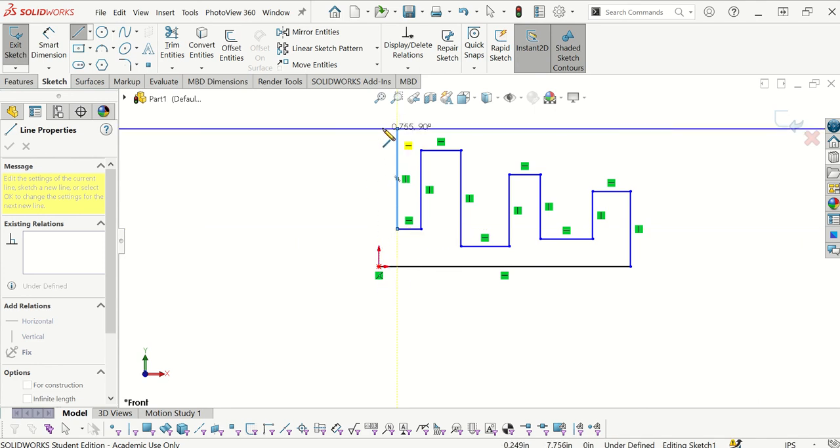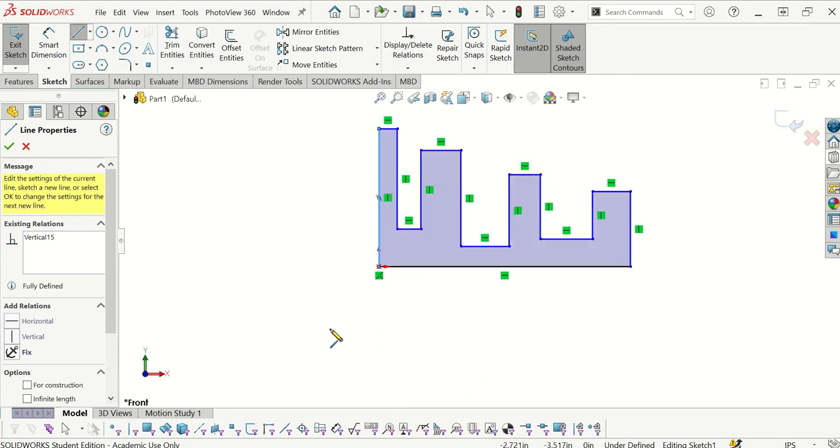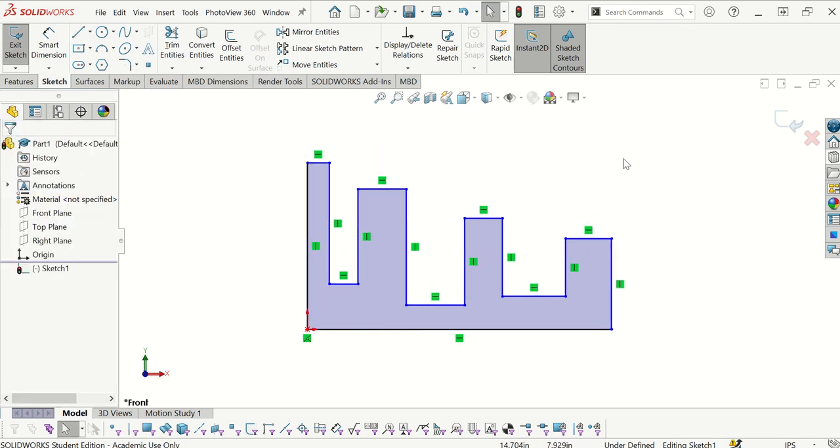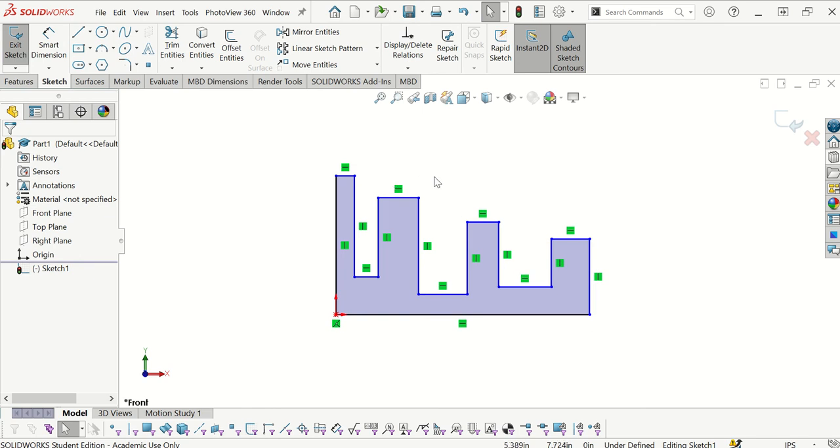Okay, and then if that dotted blue line isn't showing from the origin, you can come over here and hover over the origin, and then move your cursor up and click, and then click again. And then once you are done with this, I'm going to hit escape to exit drawing, and you can see that there's this purple color inside, meaning that this is a closed geometry. You need closed geometries in order to extrude. So make sure that yours is closed here.